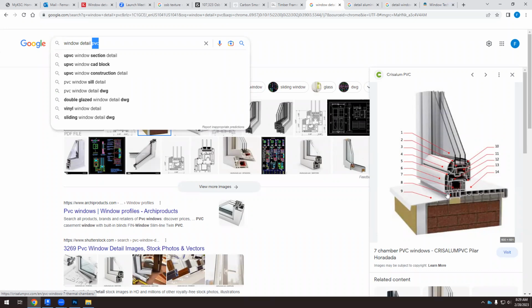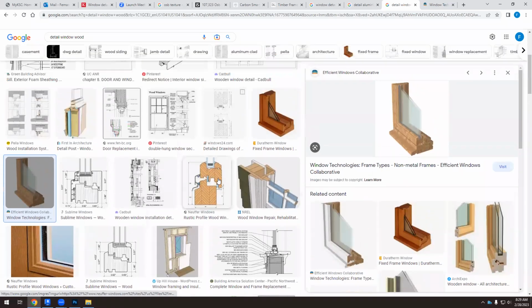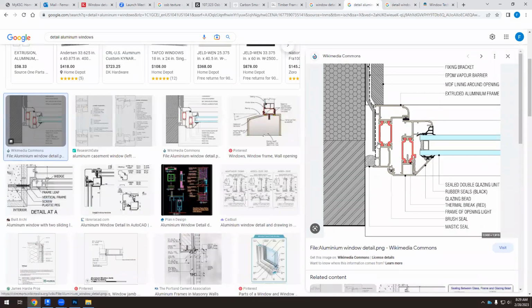Every time we have an air cavity, it acts as a thermal insulation. So if we create a lot of air cavities, as you can see, there are a lot of air cavities, we increase the thermal insulating properties of that material. So we have wood, which is very easy to understand because it's a solid material. Then we have aluminum details.